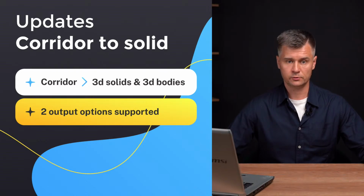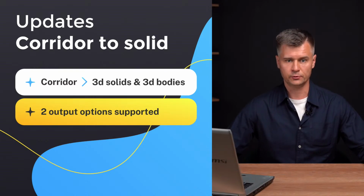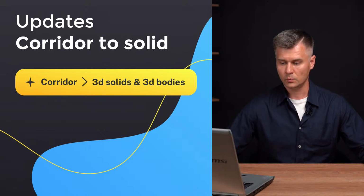sometimes it's necessary to have the possibility just to view, and it's difficult to guarantee that all the participants of some workflow will have all the necessary tools. So this process involves converting the corridor, which is typically composed of multiple alignments, profiles, and assemblies, into a set of 3D solids and 3D bodies objects. So that's in some way some kind of simplification.